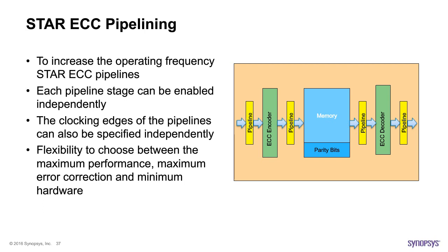and which level of correction you need to do. The multi-bit correction has its levels. Whether it is 2-bit correction, 3-bit, or 4-bit is an outcome of what the user specifies in advance. Plus, it has numerous additional capabilities, such as the pipelining capabilities and the programmability capabilities you see here, that allow us to have minimum performance impact versus power impact versus area. So trade-offs are to be analyzed and chosen accordingly. Again, a key element of testing automotive chips when they are in mission mode.